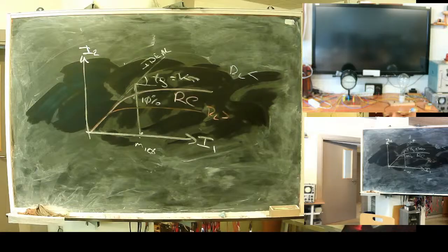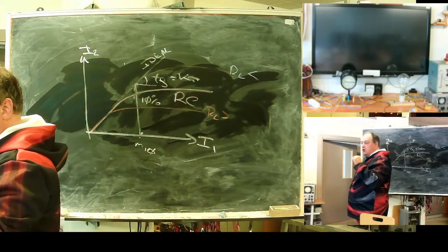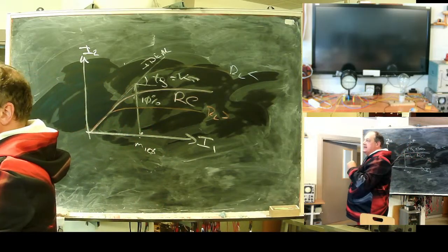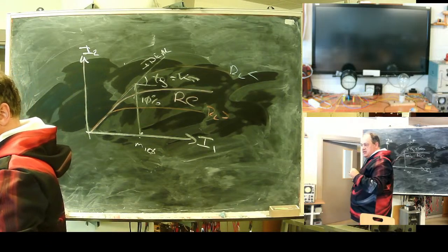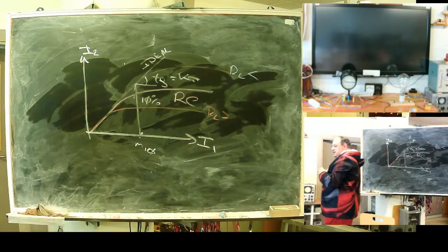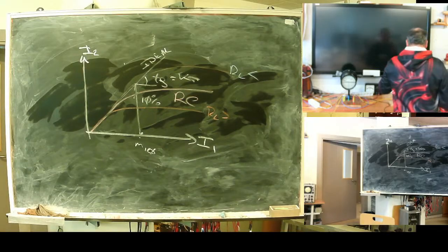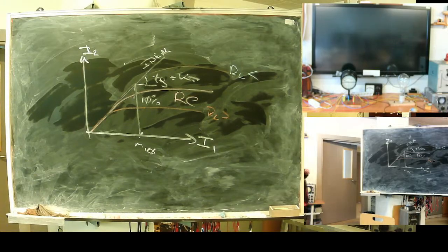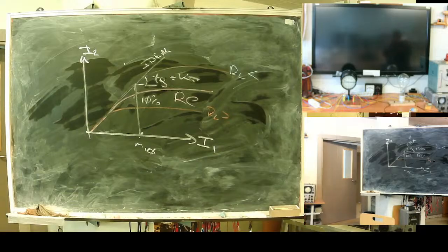Balance of what? On one side, the lower the load resistance, the lower the load burden, the lower the load on the metal core, the longer the near-linear part of the characteristic will be. But on the other hand, at one moment you see a problem. What kind of problem?